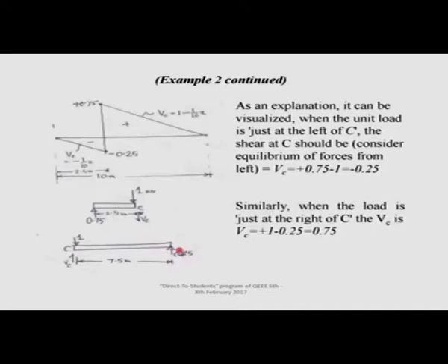You can readily see that here it is 0.25 on the right, you have 1. So, you have onto its right, when the load is just right of the section, 1 down, 0.25 up. So, you have a net 0.75 down. According to you, right down is positive. So, you have a positive quantity in its influence line diagram. That is why this is up and positive.